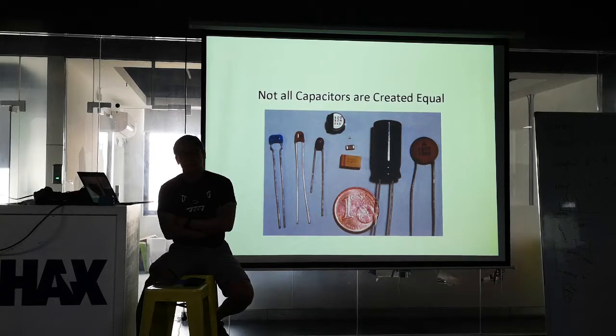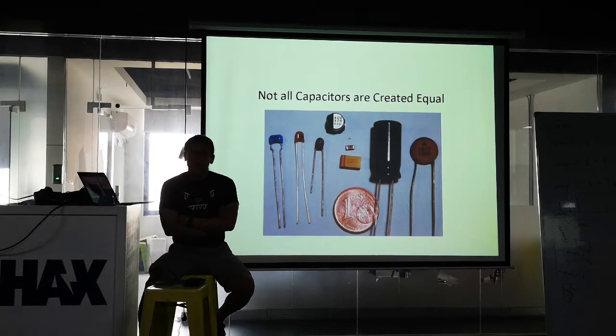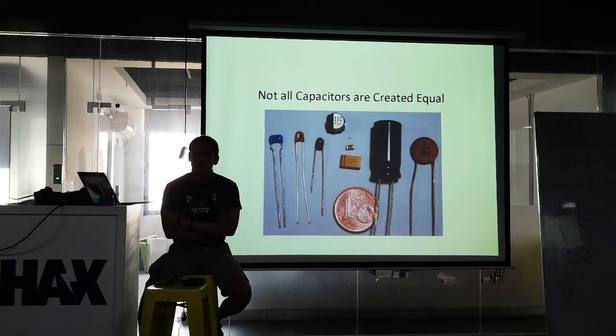Particularly when you specify ceramic capacitors, there's actually a 3-character code, like X5R, Y5V. Those are really important. They specify how the capacitor behaves over temperature and voltage. The cheap ones have almost a 100% range in capacitance: Y5V, for example, can be up to plus 80%, minus 20%.